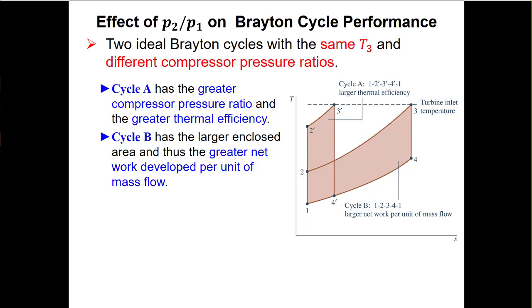So you've got this slider, or this lever, and the compressor pressure ratio is one of the levers that you can pull to try to find a good operating space where you're satisfied with the power that you're developing and the efficiency. But just like we talked about the Bugatti versus the Corolla or the Prius maybe, they have different goals. One is maximum power and the other is maximum efficiency. So you operate in different spaces and you make different choices depending on the product or the problem that you're trying to solve.